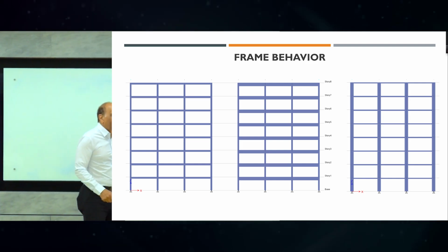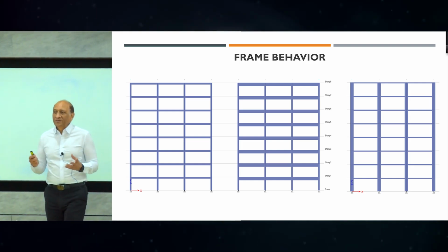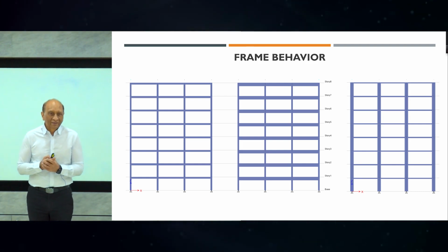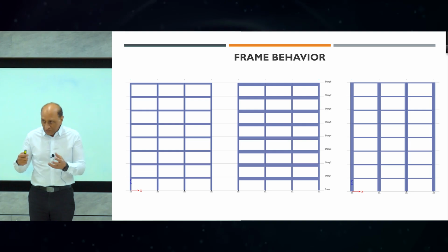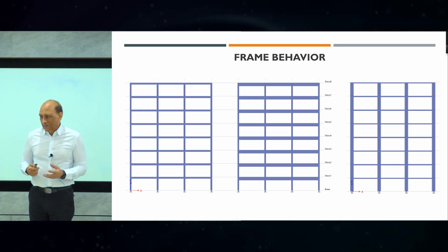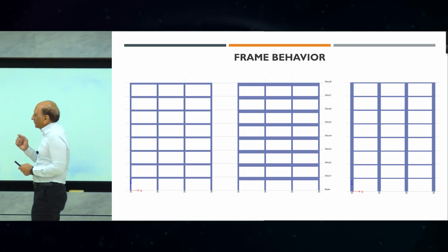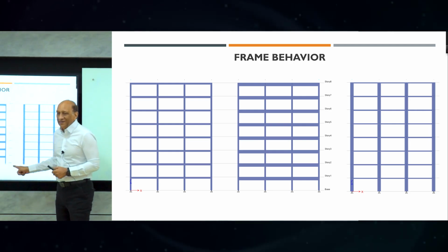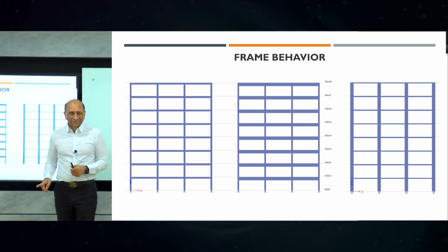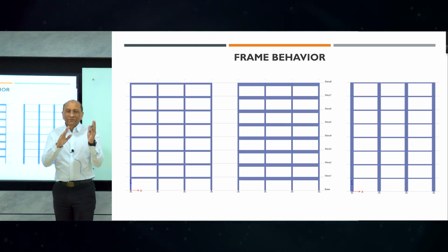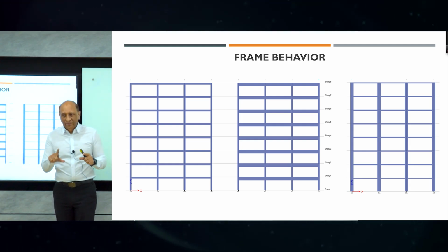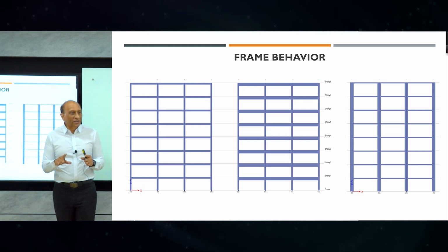And we want to study what happens to the bending moment distribution and displacement in these, so you can understand what is going to happen and what you should alter. Many people might think that making the column large will be the solution to resist the lateral loads. You will find that is not true. It's always the beam that you need to make stiff.